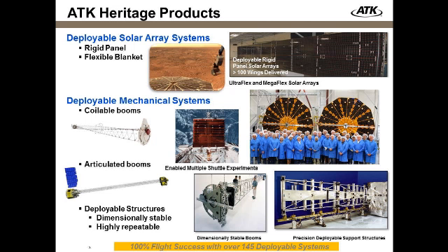We've done a variety of extended, enabling multiple shuttle missions. This is the boom that was done on the shuttle. We've done SRTM on the shuttle with a 30-meter boom, so that's over 100 feet long, with a 400-kilogram payload. So we know how to build structures that are stable, strong, and able to both deploy and retract. I think the biggest point is that after 35 years of on-orbit products, we've never had a failure, and I think that's key to our heritage and capability.